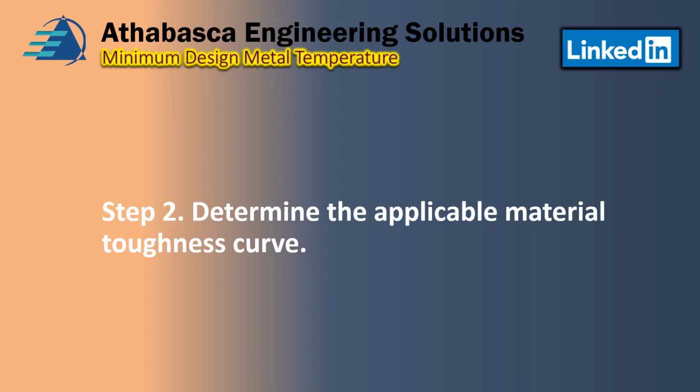You want to determine the applicable material toughness curve in this second stage using figure 3.7 for parts that are not subject to post-weld heat treat, and then figure 3.8 for parts that are subject to post-weld heat treat. And remember, this is for carbon steels, right? Low alloy stuff. And so you need to see that figure, and you need to also get the minimum yield strengths of the materials as well.